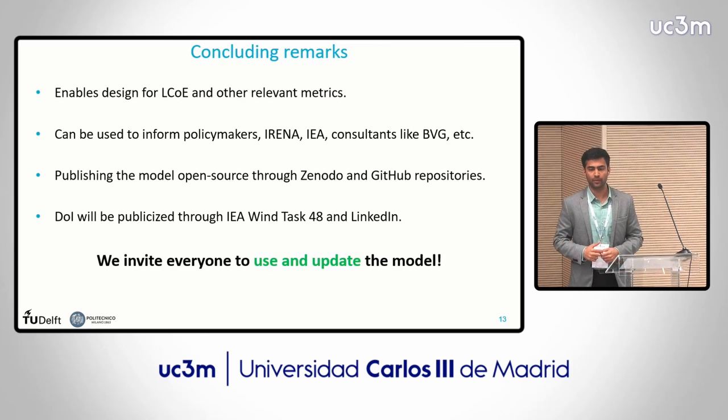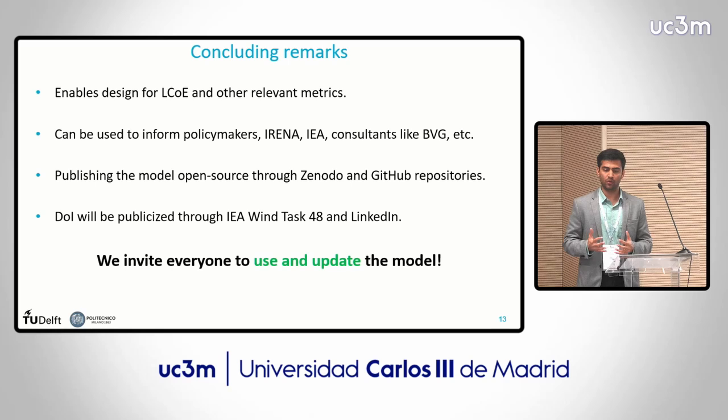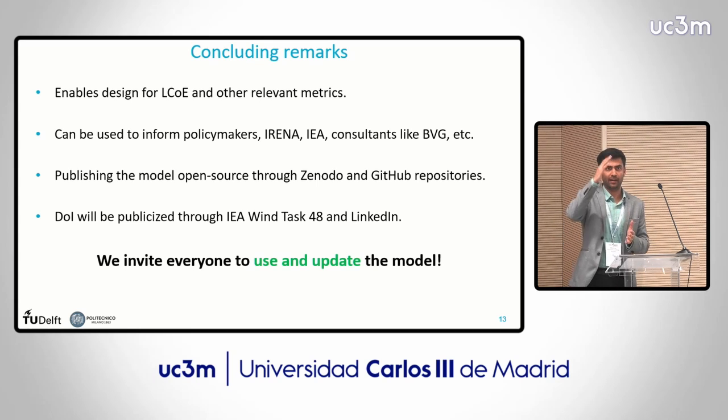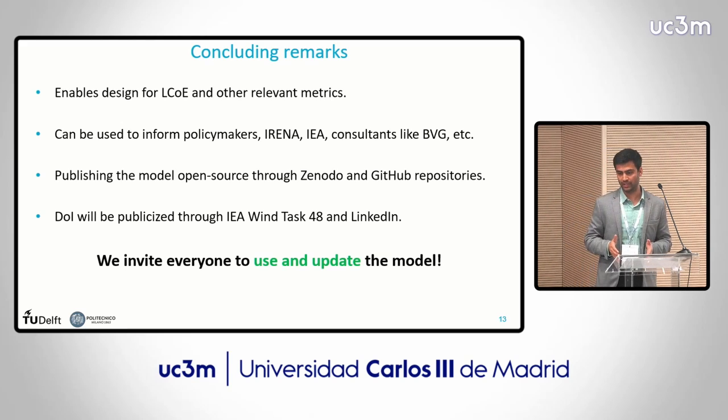Yes, so some concluding remarks. What we have now is a model which can enable design for LCOE. And what I didn't talk about is also some other relevant metrics, for example, profit-based metrics, which make sense when you have fluctuating electricity prices. Then sometimes it's better to produce electricity when the prices are high, and that's usually at low wind speeds. So if you make this a design objective, and you start designing your system for a different metric, you'll have a completely different system design.